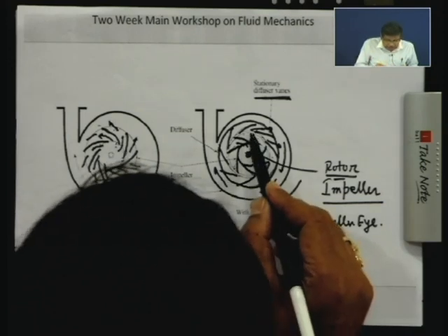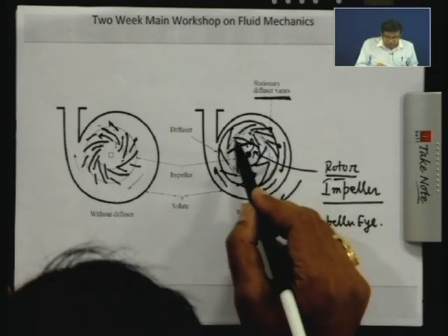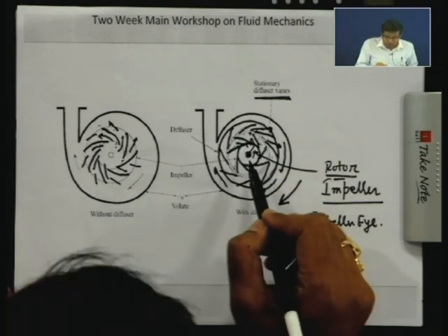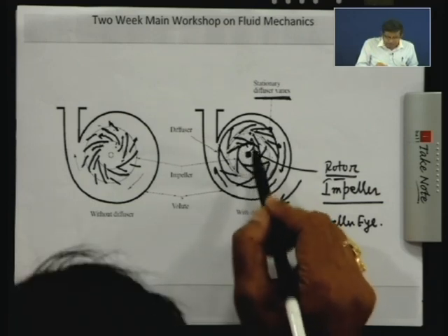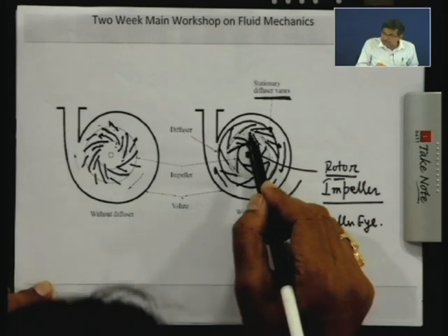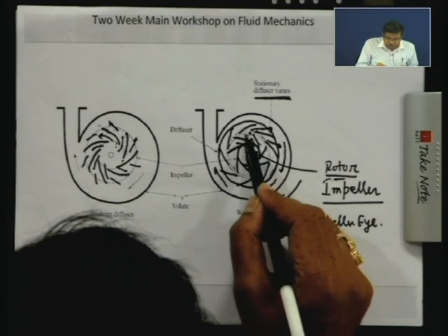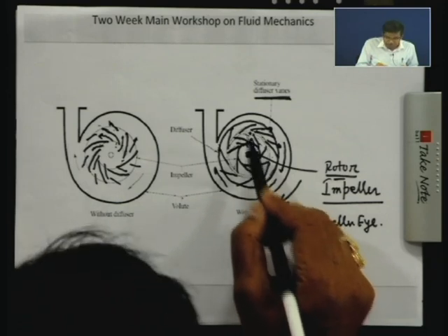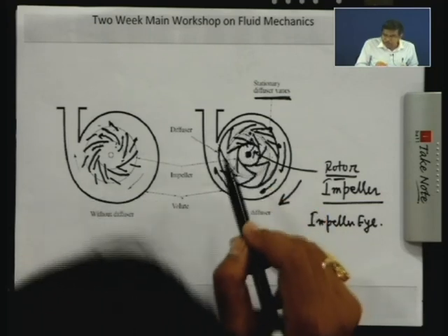Now, while coming out of the impeller, the liquid or the water has high kinetic energy, as I have just told, because of the impulse action, that is the kinetic energy imparted by the rotating impeller blades to the liquid, and at the same time it has a higher pressure energy or higher static pressure because of this diffusion, that means increase in pressure because of its flow through a divergent duct. Now, when it comes out from the impeller,